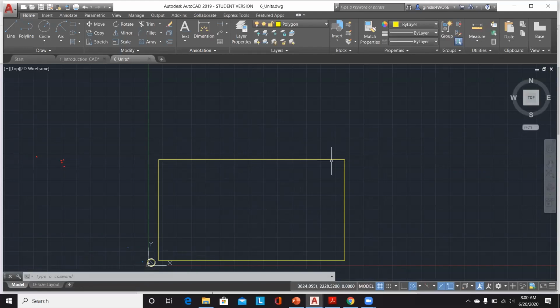And you can use this to convert angles from degrees to radians, or let's say you have to convert millimeters to meters. So what you do is you're drawing to scale 1:1 in your modeling space. And if you want to convert a system of units from one to another, all you need to do is use the scale factor, which we accessed using the scale command, which will be really helpful for you in accessing the units. So right now what we have discussed is how to use the drawing toolbar to set up units and how to convert units from one system to another.